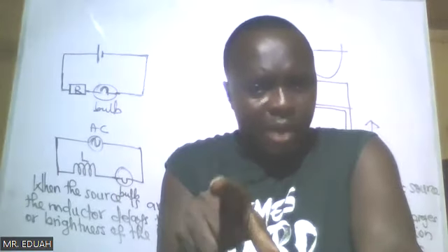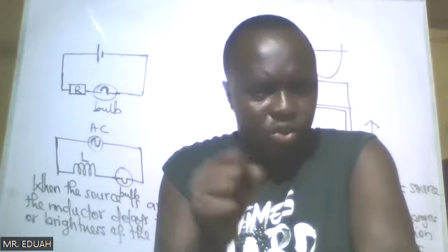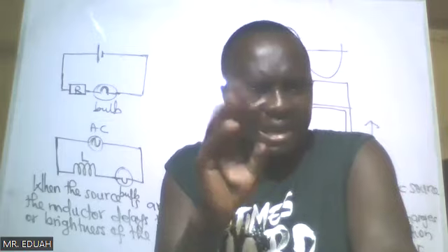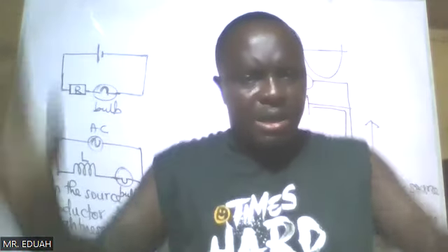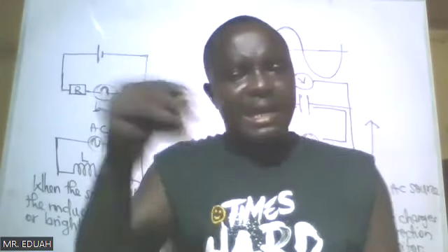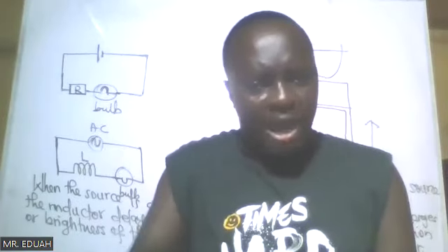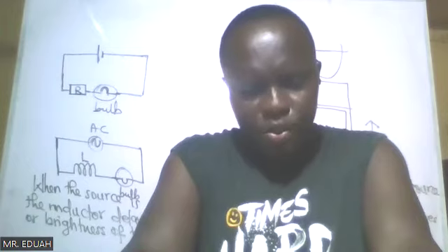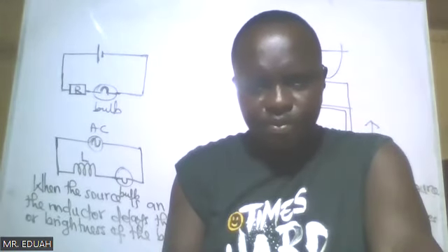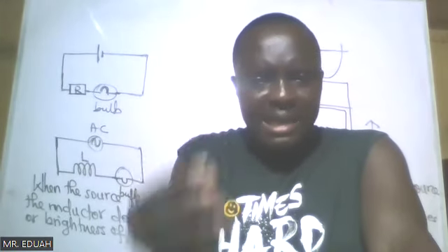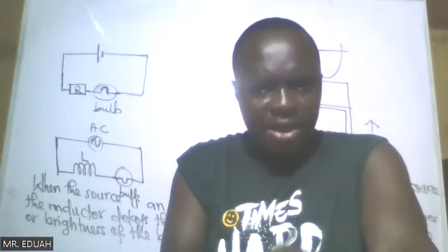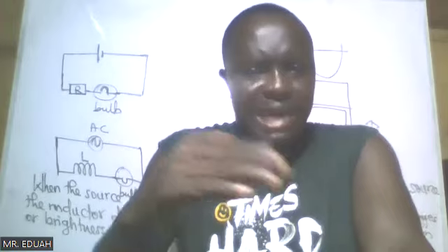That's why when you switch on a fluorescent tube, it takes time to brighten. Then it comes on quickly. So it's the inductor which controls the flow of current from minimum to maximum. So the inductor delays the current, so as to build up gradually.